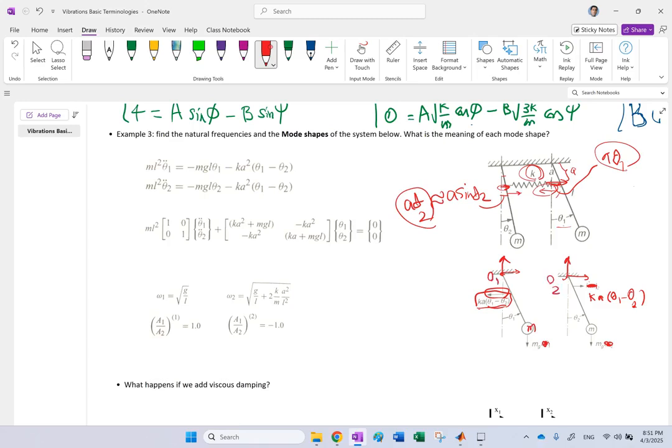If you do that, remember from the pendulum vibration problems that we did in previous videos, only mg sine theta has a moment. The cosine one has nothing. So only this sine theta will have something. But remember, sine theta is the same as theta here because its angle is small. So this term will be multiplied by this distance L, and that is a negative moment.